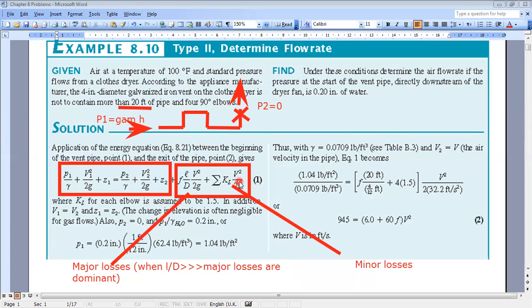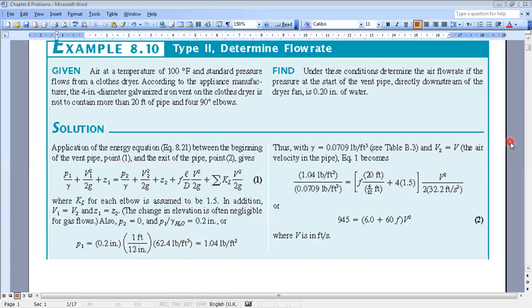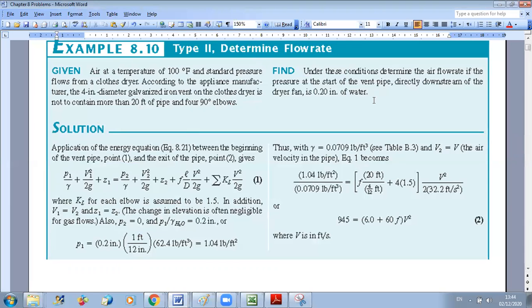Now, in order to know what is the loss coefficient for an elbow of 90 degrees, I should go to tables. In general, they give me tables or figures to find my loss coefficient. So let me go to the table which will give you the value of KL. In general, in the exam, we give you figures, and you will see that some figures will be repeated during the examples, and all are present in the book.